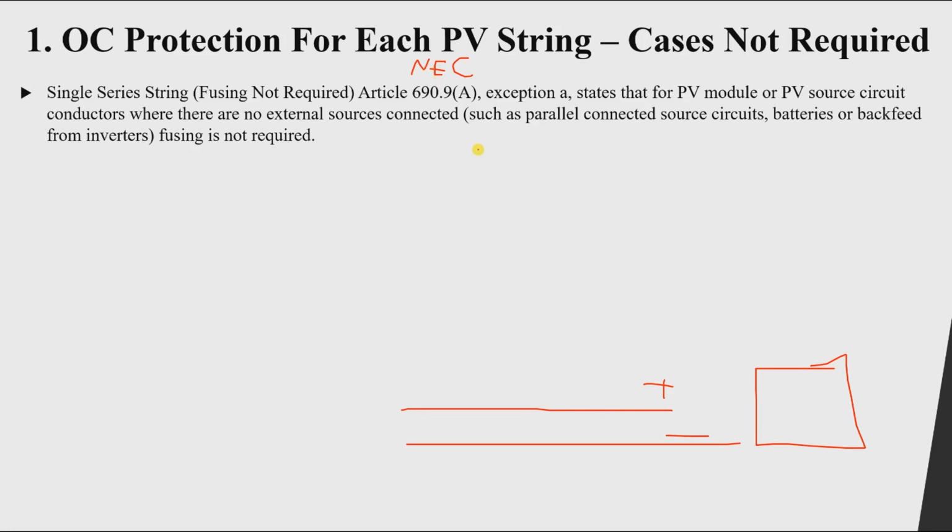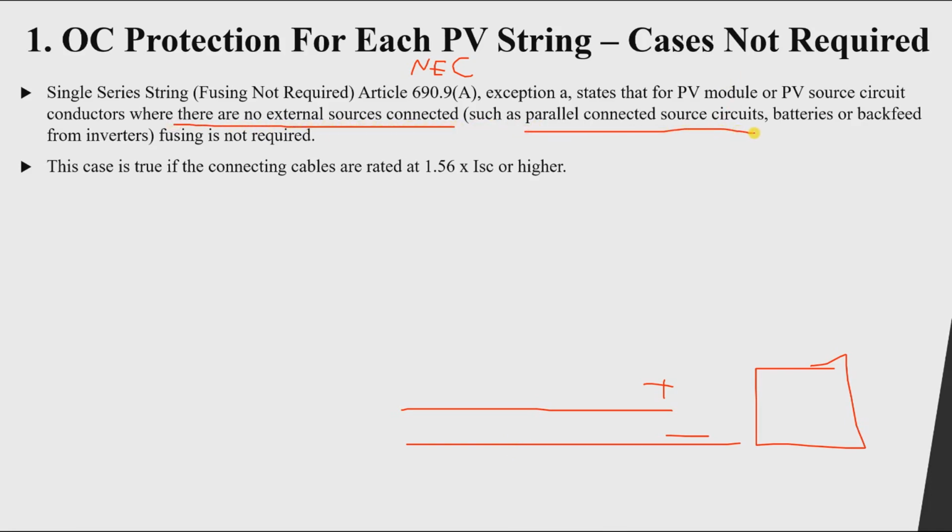Okay, however, there are some conditions. The first condition is that this string should not be connected in parallel with other sources. So there are no external sources connected, such as parallel connected source circuits, batteries, or any backfeed from inverters. In this case, you don't need a fusing.